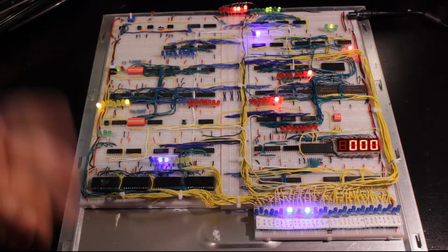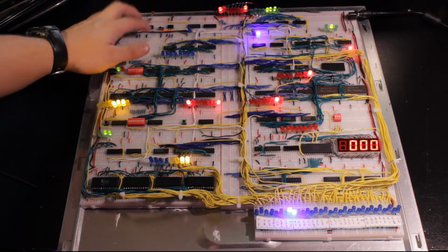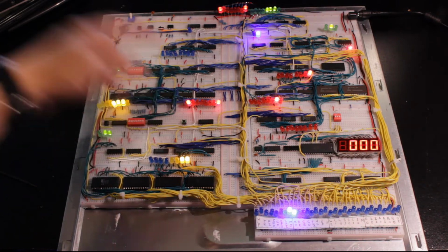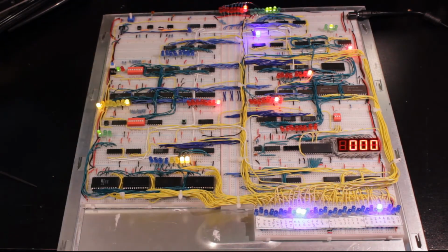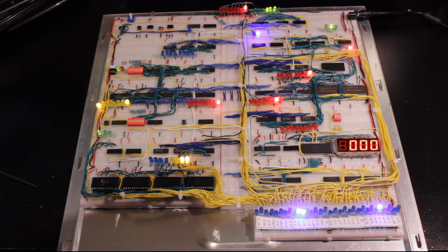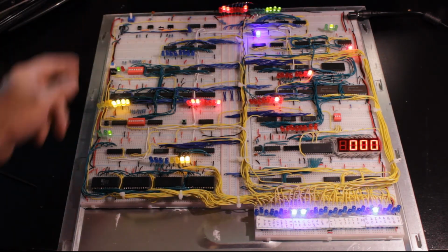Now we're back to doing a fetch cycle. We're going to get the next instruction, which is a store A command. We're going to get the pointer to where that's going to store it, the second variable, 0x81, and that's going to go into the memory address register real quick here. And then we're looking at that value there, which was a 1, that we just took from the A register and put in that second variable. So now we hold a 1 and a 1, and we're going to get to our conditional jump instructions.